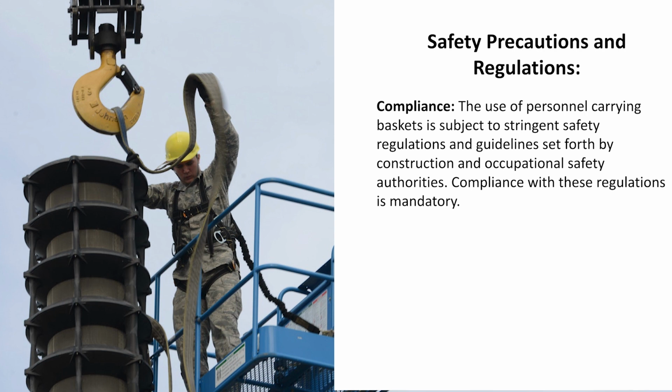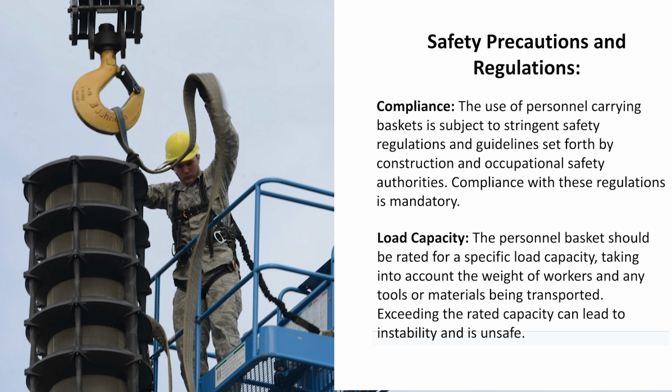Compliance with these regulations is mandatory. Load capacity. The personal basket should be rated for a specific load capacity, taking into account the weight of workers and any tools or material being transported. Exceeding the rated capacity can lead to instability and is unsafe.